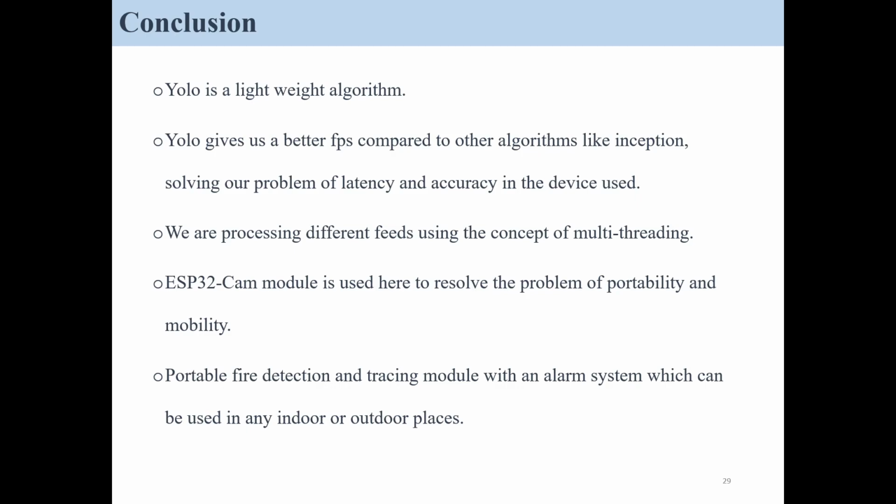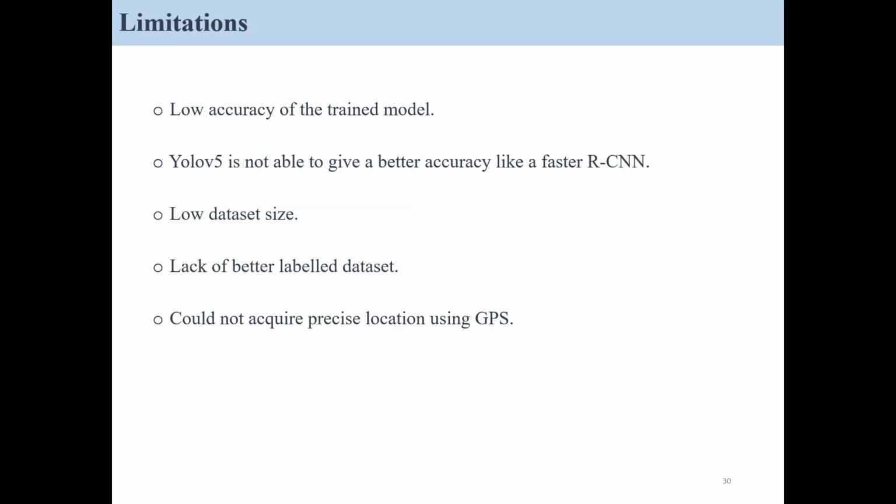In conclusion, we have found that YOLO is a lightweight algorithm. YOLO gives us a better FPS compared to other algorithms like Inception, solving our problem of latency and accuracy in the device used. We are processing different feeds using the concept of multi-threading. The ESP32 CAM module is used here to resolve the problem of portability and mobility, a portable fire detection and tracing module with an alarm system which can be used in any indoor or outdoor places.